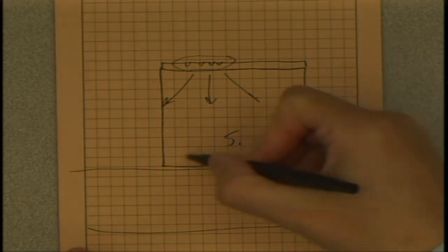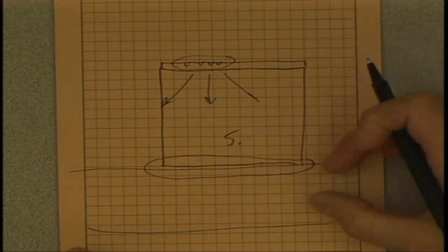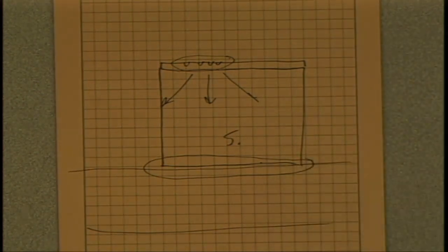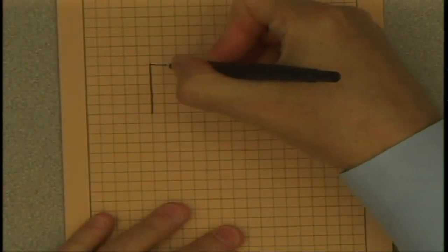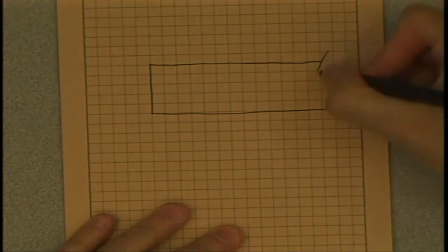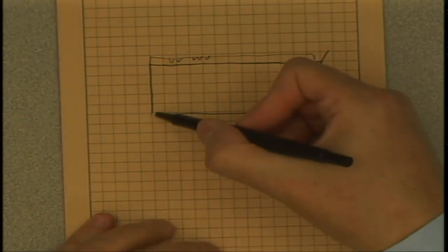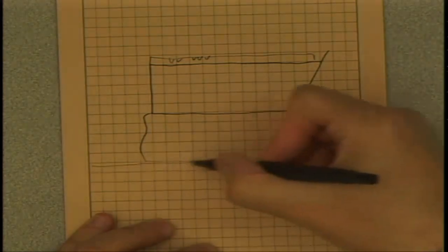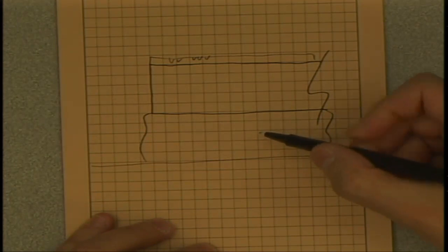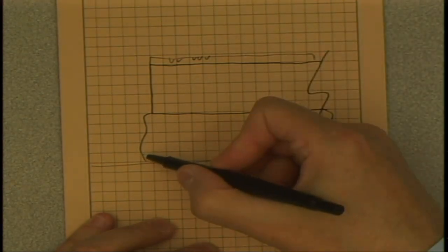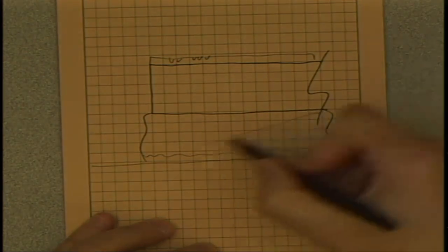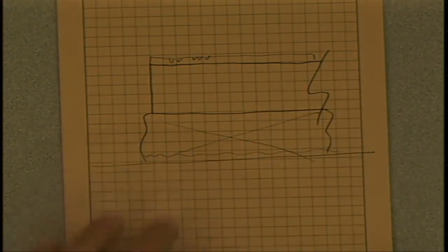There's quite a bit of work going on right here on how you attach the die to the copper as well. Normally they've been soldered for years and years. But if you look at a modern IGBT that's, let's say, 70 microns thick, and I'm just drawing a cross section here, and here's all the junction engineering on top with the trenches and so on, the solder itself is about 50 microns, and then you've got the back plate. So this becomes a limiting factor. So the technology trends now are to make the die thin, of course, but then to use techniques like sintering. So this becomes 10 microns instead of 50 or 60. So some interesting work going on there.